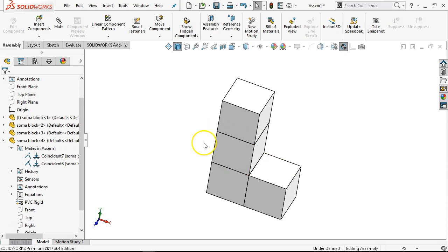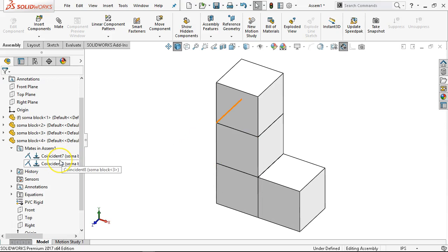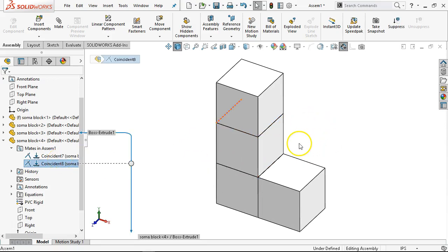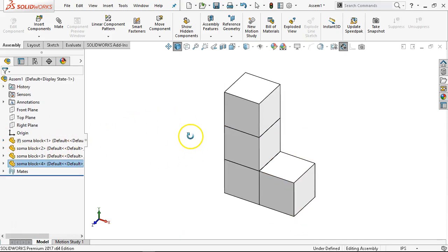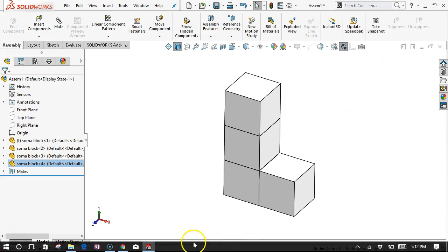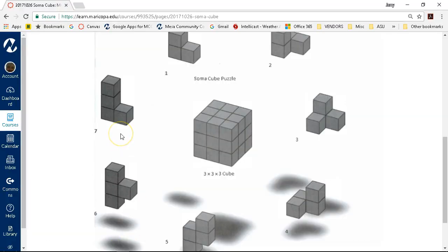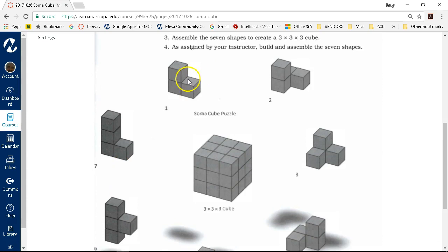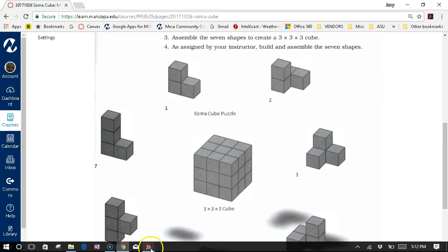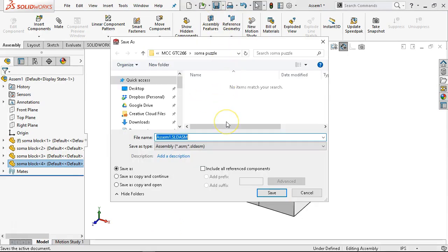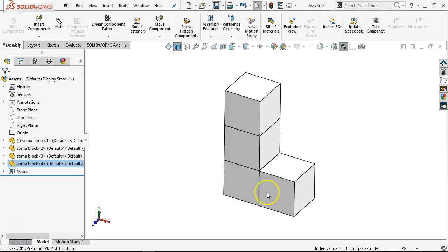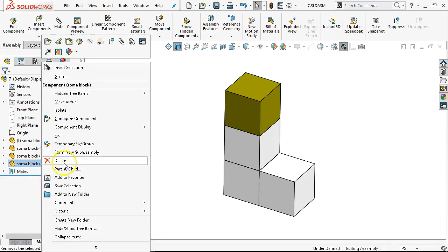Problem is that if something happens to this mate, this is going to be able to rotate freely on that dynamic motion on those faces. So I'm still going to say edge to edge is less of a preference. Okay, so this becomes, actually, I started with 7. I guess we should have stopped at 3 and gone to 1. All right, so this is going to be SubAssembly 7. And if we wanted, since 4 is in the mix, I can delete it.